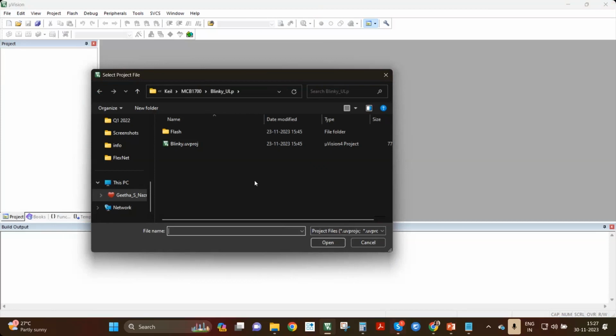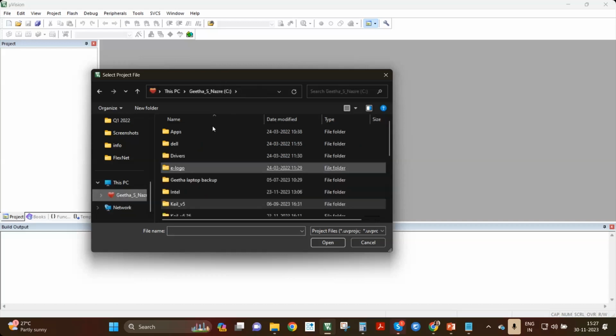If you are opening the Keil IDE at your end, you may not see that if you're using MicroVision 5. For that, you have to download the legacy pack, because LPC1768 was a legacy device. This device was supported in MicroVision 4 first. To get this device listed in MicroVision 5, you need to install the legacy pack.